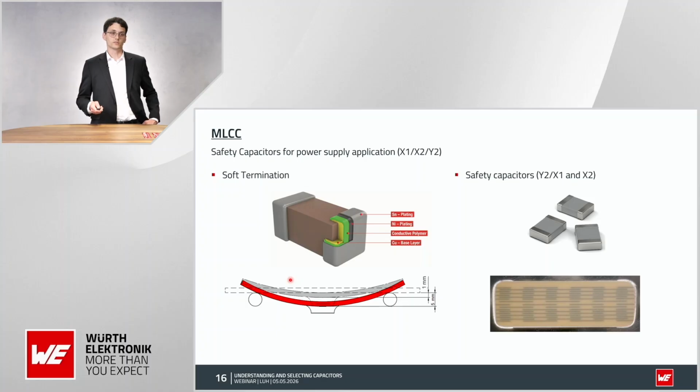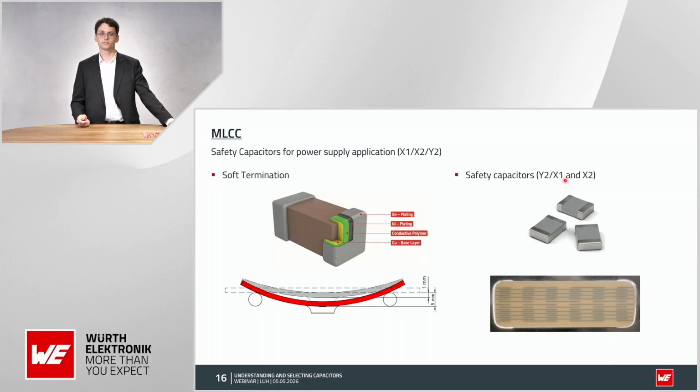Yeah, we have also some safety capacitors for MLCC, which are shown here on the right-hand side. Y2 or X1 capacitors and also X2 capacitors. Especially for the Y2 and X1 capacitors, we have the internal series connection, because if you might have some cracks, for example, this gives the benefit that you won't have a short circuit, which would be very dangerous for especially Y2 capacitors.